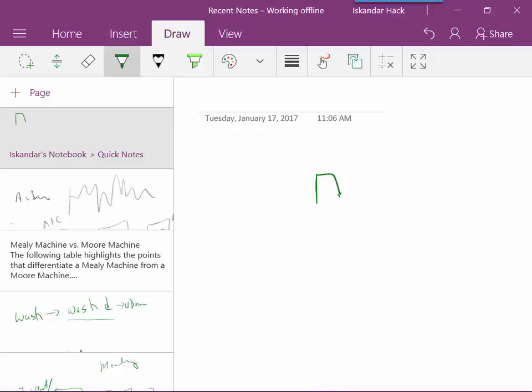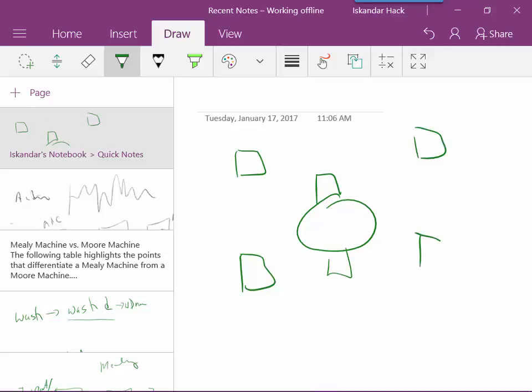Okay, here's our motor. Our H-bridge, I'm just going to show these as little boxes, and I'm going to call them S1, S2, S3, S4. Now, they would be JFETs in the normal drawing, but for the sake of the final exam, it could just be boxes. So to go in one direction, S1 is turned on and S2 is turned on. To go in the other direction, S3 is turned on and S4. So we simply turn on two of the switches to control the direction of the motor.